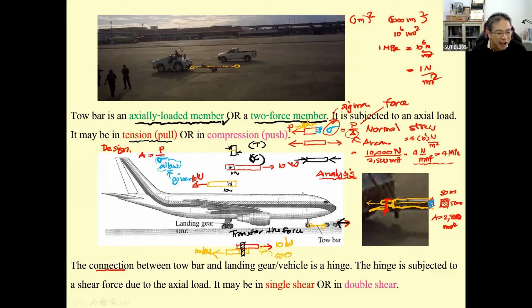And then we just consider the top portion, I cut it over here. And then the force that occurs over here is going to be this one. And this one is the force that's parallel to the surface. When you try to pull, this is two-way, okay? You see the red, okay? One is going to move here, one is going to move here. That is going to produce this one. We call this one the shear force.